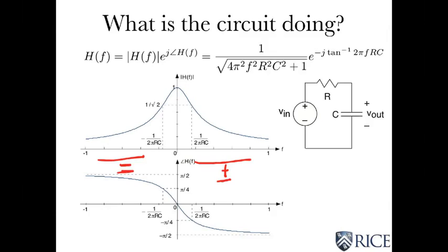So negative frequency certainly exists, and you should plot your magnitude and phase realizing that there are both positive and negative frequency components. However, it turns out there's a pretty easy thing to see in this example, and it's going to happen in general. And that is, for the magnitude, it's a symmetric function about the origin, having what we call even symmetry.